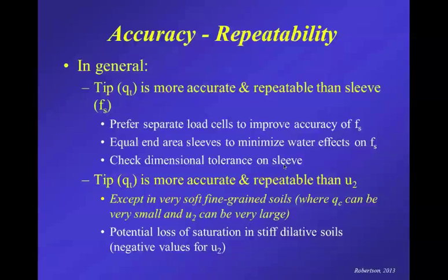Now, that's not very much, but it's a noticeable increase. So it's noticed to be a little bit larger than the tip. And I'll comment about this a little bit later. My preference is that sleeves should have the same diameter as the tip, because if it's slightly oversized, and some manufacturers do make their sleeves slightly oversized, still within the tolerance, the downside with that is that with wear, they will wear, and so they may start off being slightly oversized, but after a few soundings they begin to become equal to the tip, and so there's some variability even though they're within the tolerance of the standard.